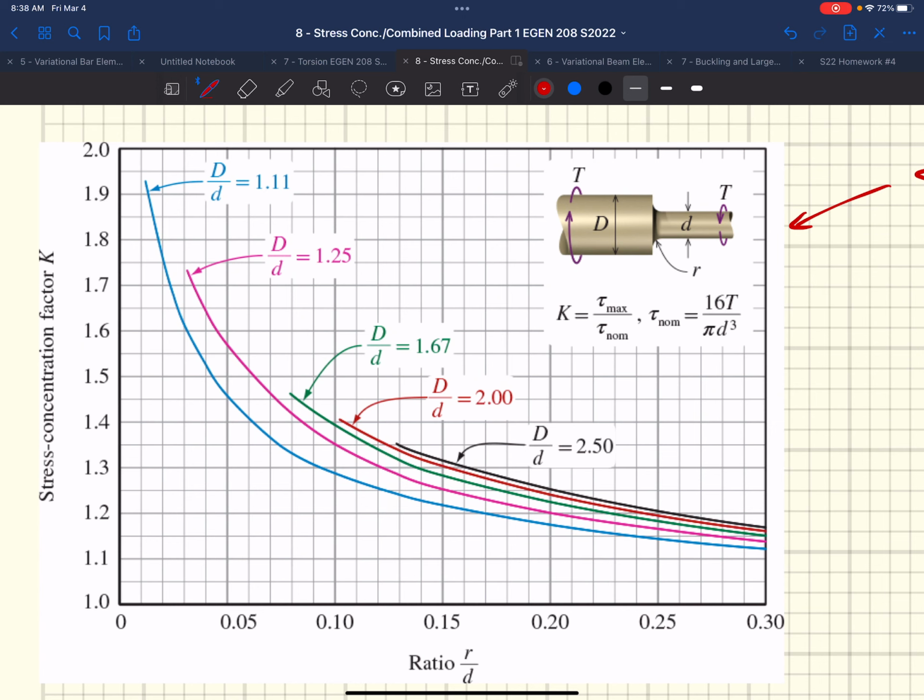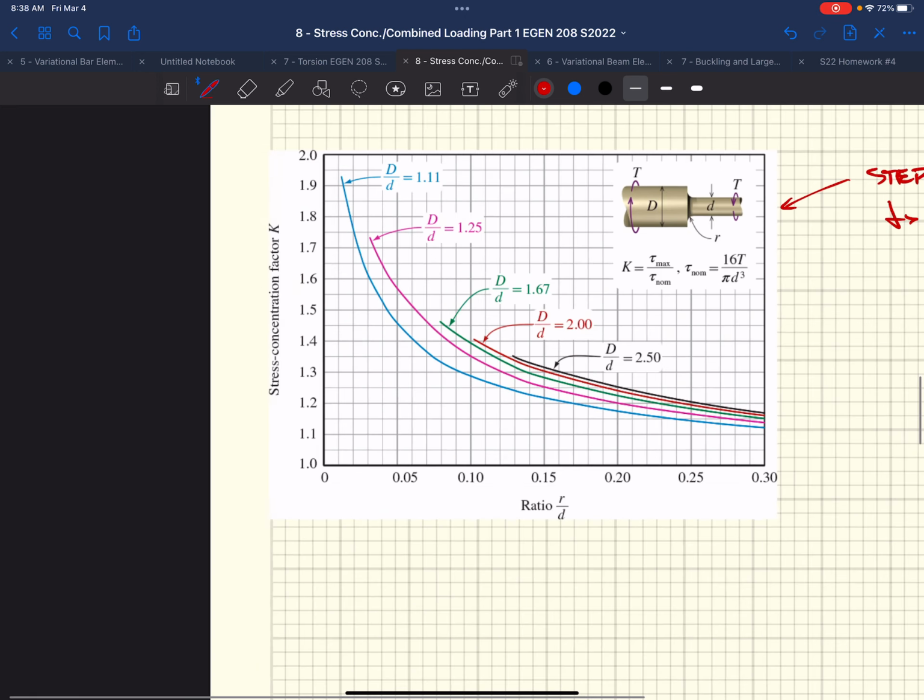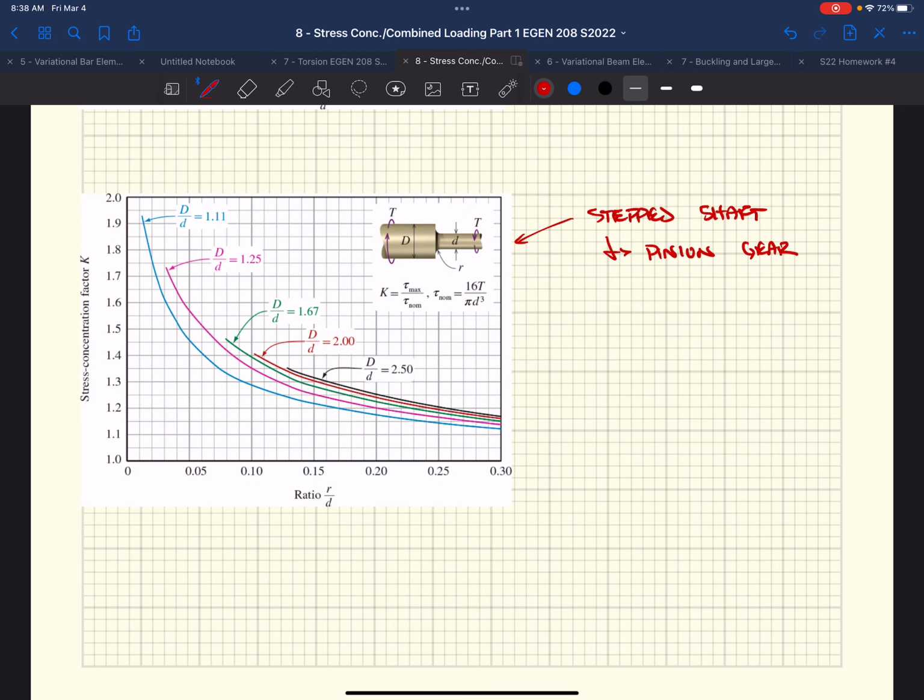So whenever you're putting a notch in anything, or changing dimensions, put a radius on it. Otherwise you get high susceptibility to cracks that form right at that notch, a 90-degree angle. As you can see here, that stress concentration goes through the roof, and you could nearly double the stresses just by having a very small radius.